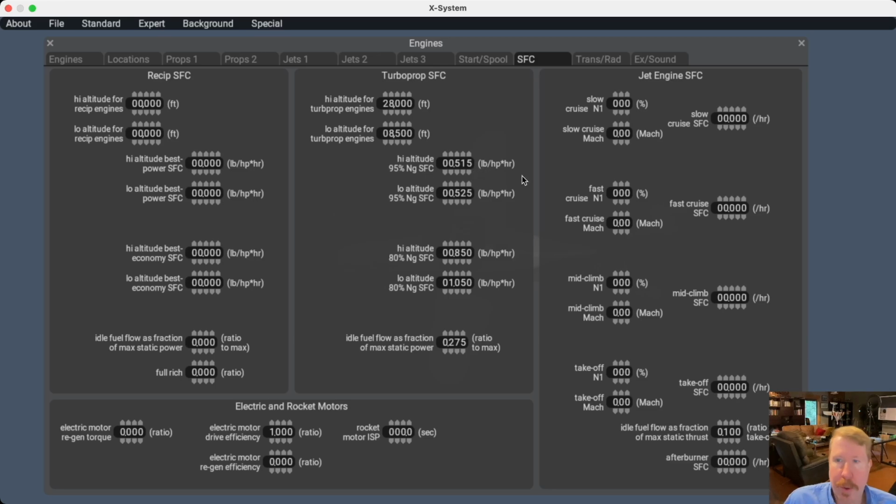Pounds per horsepower hour. Again, take the number of horsepower, multiply it by this constant, and you get the pounds per hour. Divide by about 7, and you get the gallons per hour. So treat these numbers to get the right gallons per hour or pounds per hour, if that's how you measure it, at fuel flow for your engine.